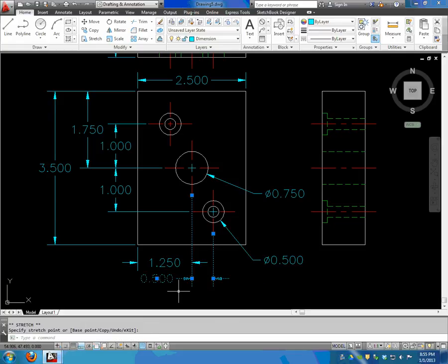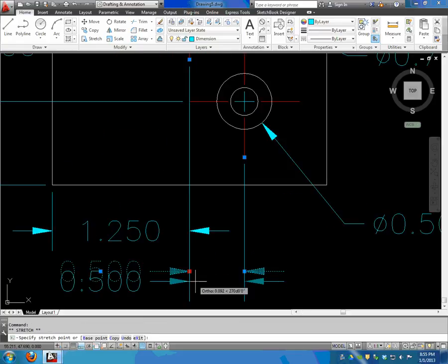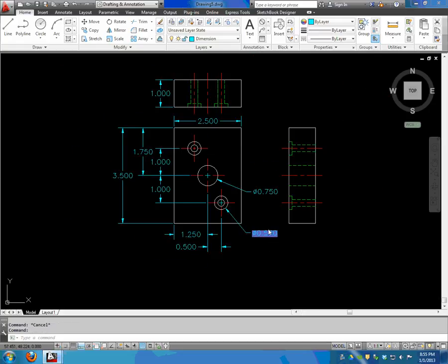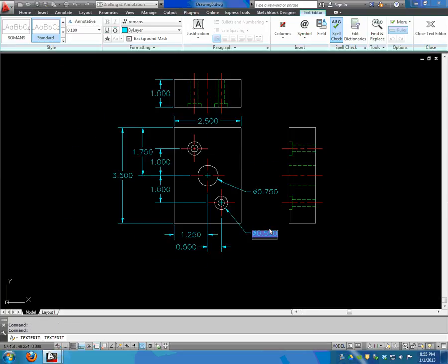What I'm going to do is I'm actually going to pull that over and pull this down. And if I double click on this, I can go up to tweak it space so I can put my counterbore, hit enter, go up to the top, percent D, oh, percent C, 0.250 through, and there, space, and then we'll do counterbore depth, 0.125, and we'll put 2 holes.